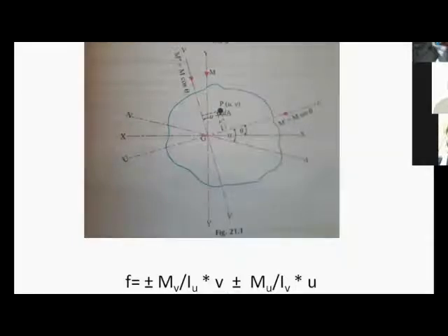So top compression, bottom tension. When it is loaded horizontally from this side, now it bends this way. So compression on the right and tension on the left. Or the same load, if it is acting this way, it pushes the member like this. So compression this side and tension on the right-hand side. Okay, so that is how you decide the signs. This we will discuss again when we discuss the problem.